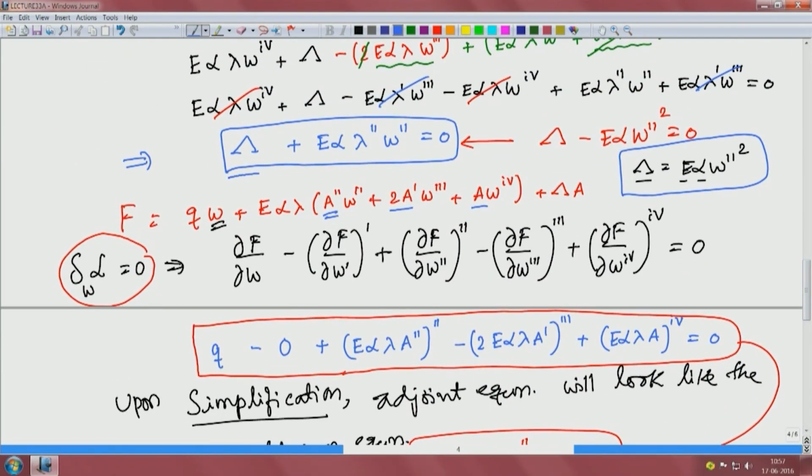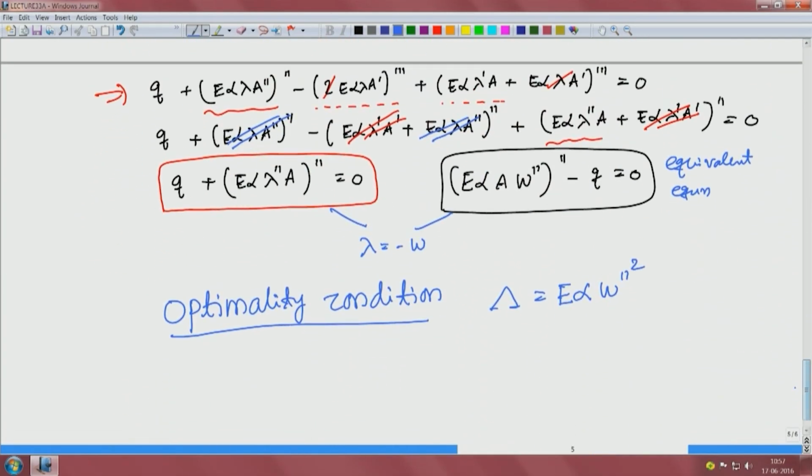We had this as the design equation and then we substitute for lambda equal to minus W, and W double prime, that gave us this, okay. Again let us remind ourselves that alpha is d square by 12, because in this problem we have assumed that d is given, it is part of data. So, this is the condition we got by manipulating the design equation, but there is no design variable A here. This is exactly what we had for the bar as well,